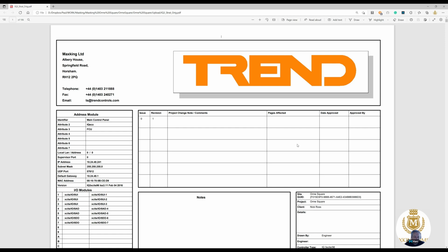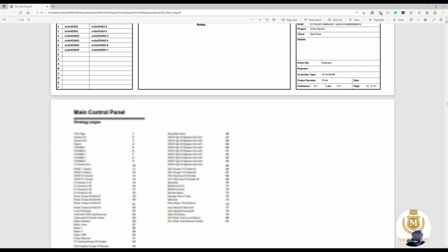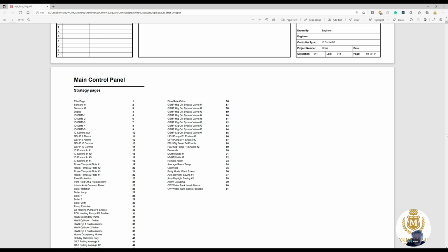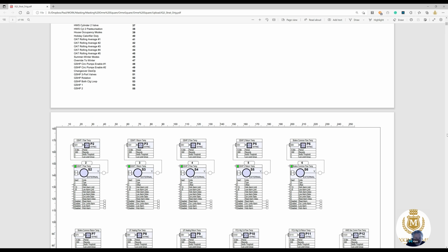I've got a job tomorrow to take the ground source heat pump from the Trend IQ3 controller across to the MAC36NL ISMA controller, and I'm just going to go through the Trend PDF file that I've set up to see what points I need to take across.